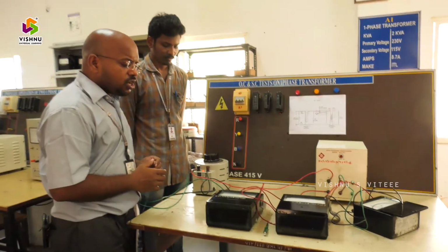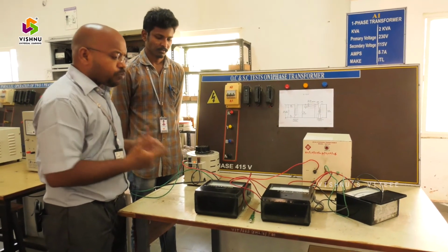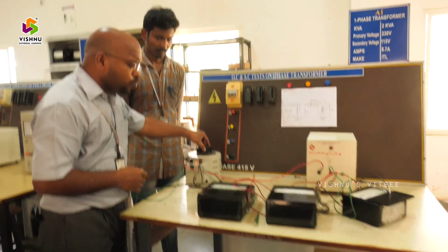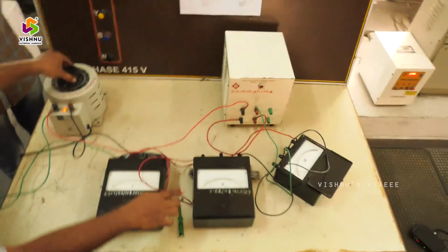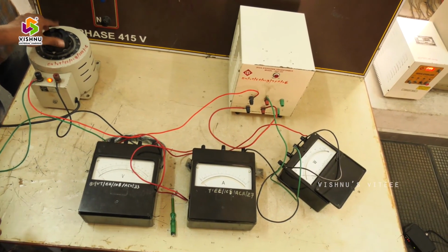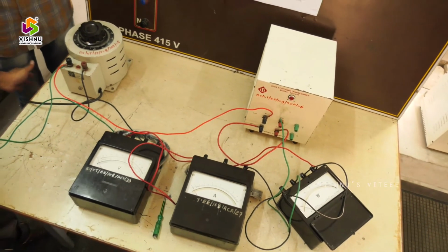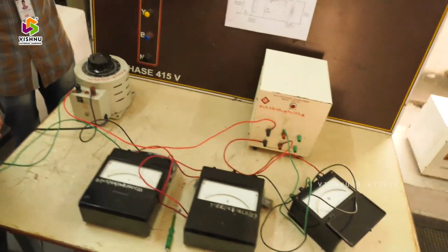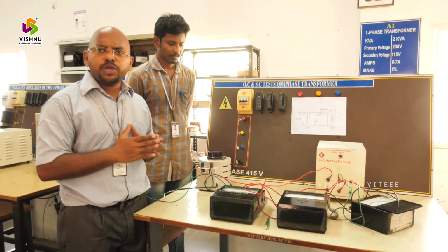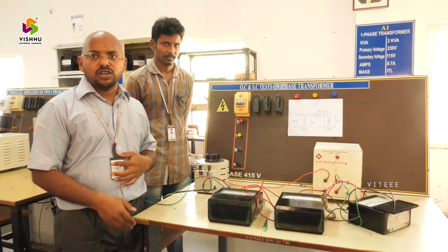After getting the voltmeter, ammeter and wattmeter readings and noting them all down, you have to bring the auto transformer from the maximum position back to the minimum position, until the current drawn by the transformer is 0 amps. After minimizing the auto transformer, switch off the power supply. So now we have completed the short circuit test on a transformer based on the readings from the open circuit test and short circuit test. The calculation part will be discussed in the next section. Thank you.